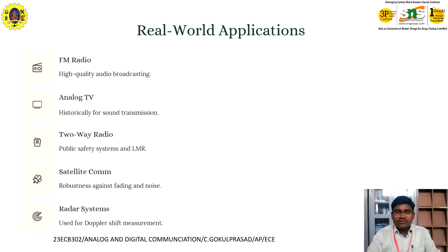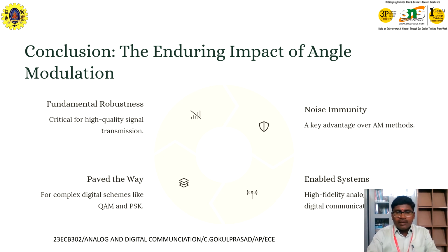The conclusion about the impact of angle modulation is that it provides better noise immunity when compared with AM methods, that is amplitude modulation. By employing angle modulation, it is highly resistant and offers high fidelity in analog and digital communications, and paved the way for different digital schemes like QAM, PSK and so on. Moreover, the robustness is drastically greater with angle modulation, so we are able to achieve higher signal quality at the transmission end.